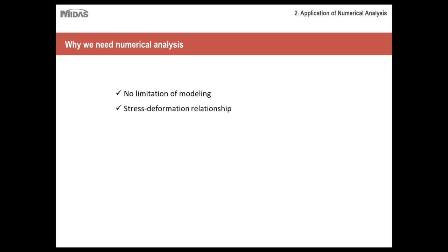Okay, the stress-deformation relationship. Soil element stresses as well as structural stresses and deformations can be analyzed in detail with numerical modeling. This becomes more and more prevalent for certain projects where you would need to calculate the displacement, for example settlement-type projects, retaining wall projects for deep excavations, etc. Soil structure interaction. For large, heavy foundation-type projects, soil structure interaction is essential. A lot of design codes require, depending on the region you're in, that you run a soil structure interaction analysis. And this can be very easily done with numerical modeling.